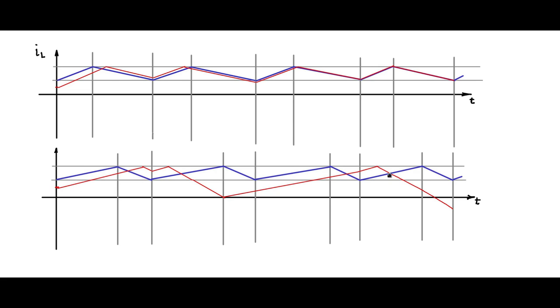And you see that the disturbance starts growing. Cycle by cycle it starts growing, it becomes unstable. So it never converges to the expected steady state value of the inductor current. So when the duty cycle is greater than 0.5, the inductor current will start diverging, and it will not be stable when you do current controlled operation in this fashion, where this is the IL reference. The top of the inductor current ripple is the IL reference.